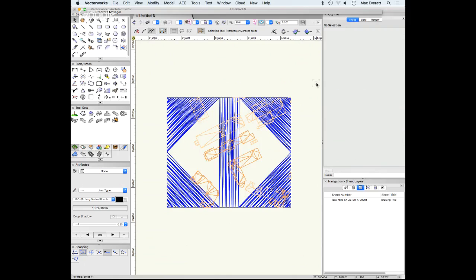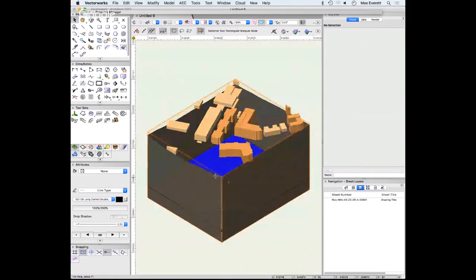And you can save the style. Like anything in Vectorworks, you can save a style. If you create a stair in one project and save it as a style, that stair can then be used across any scheme with one click, rather than having to change all those graphic attributes again. Not necessarily the height parameters, but how a style looks, whether it's got a metal balustrade. It's the same with sites. You can create a style and apply that across projects. So that's how you create a site, edit a site, and manipulate its graphics. Any questions or comments or tips?